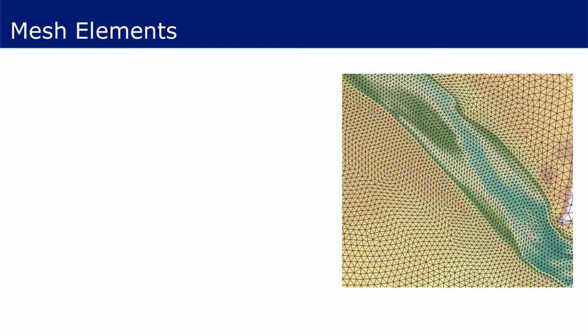With the extent boundaries established, the mesh element number and size are two other aspects to evaluate when converting a hydraulic model to a sediment model. SRH2D is robust enough to handle model meshes with up to hundreds of thousands of elements, and there can understandably be a desire to create a fine mesh resolution to ensure that the results are as accurate as possible. However, the instinct to build a large mesh with many small elements must be balanced with the practical usability of the model and the effect on the model results.